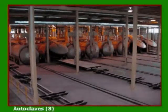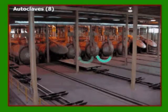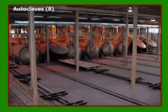Here's the most important part of the process, the autoclave. Also here we are very energy efficient. Before discharging an autoclave, which holds 12 bar of pressure and a temperature of 350 Fahrenheit for about 10 hours, we reuse the remaining steam by loading a new autoclave with the material, closing the autoclave, and then using the steam from an autoclave which is ready for discharging. So we push the remaining energy from autoclave to autoclave.